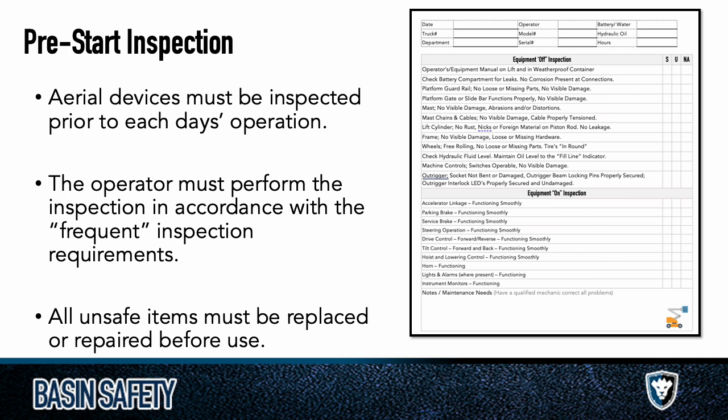Just my personal soapbox of mine. Check the air. Check how full it's supposed to be, and people just don't do it. You'd be surprised. I'll go to a forklift, man, it looks almost fine, but then you check it, and it's like 30 or 40 or sometimes 50% of required tire pressure. So just keep that in mind. Make sure you get that fixed and reported right away. Do it before every shift.